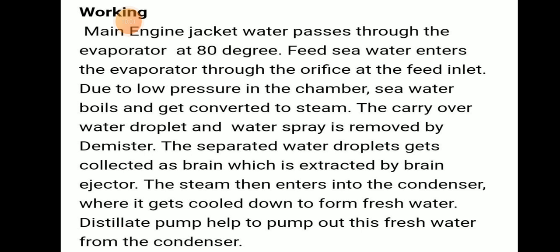The carryover water droplets and water spray are removed by the demister. The separated water droplets get collected as brine, which is extracted by the brine ejector. Steam then enters the condenser where it gets cooled down to form fresh water, and the distillate pump helps to pump out this fresh water from the condenser.